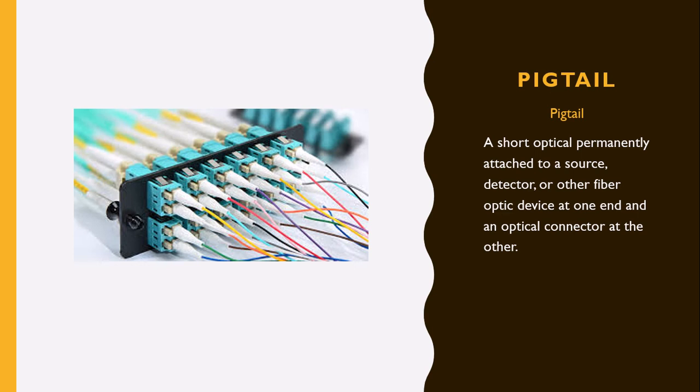High quality pigtail cables are coupled with correct fusion splicing practices. Pigtails are usually found in fiber optic management equipment like the ODF, fiber terminal box, and distribution box. Fiber optic pigtails are also available in various types, such as LC fiber optic pigtails, SC fiber pigtails, and ST fiber pigtails, etc.